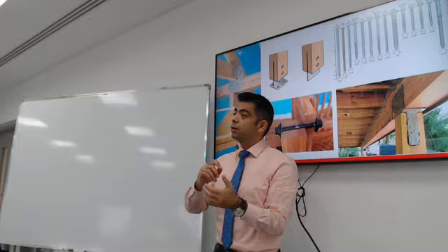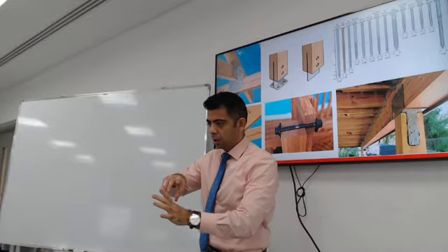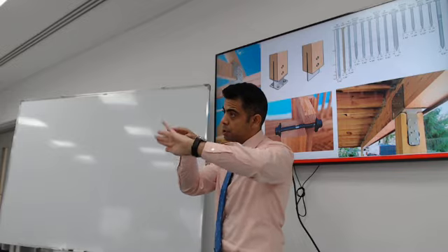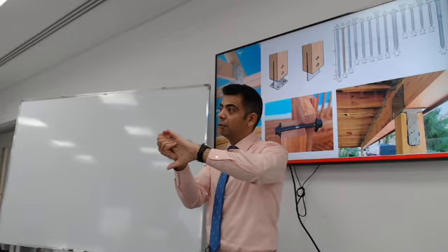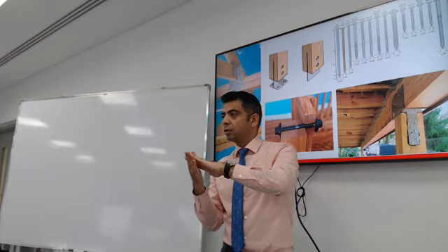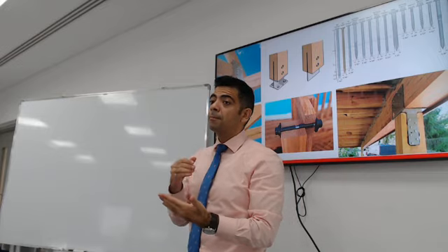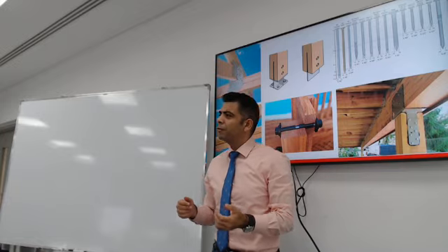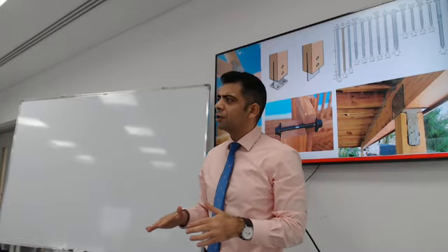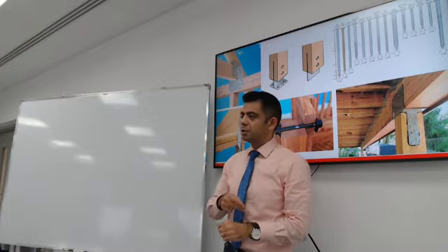You can use something called lag screws that will not just punch through the wood, but will help retain the bond or the connection, especially if there is reversible loading. Some connections actually result in squeaking. If you walk on a wood floor, you might hear squeaking. Maybe you need a screw rather than just a nail.